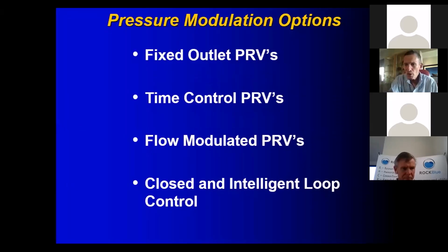Now, when you're using a pressure reducing valve with a pilot, you typically create a fixed outlet pressure going into the zone. So you have a zone of maybe 5,000 or 10,000 properties, and you have a fixed pressure going into that zone. The objective is that at your critical point, you get a pressure of roughly 20 meters, 25 meters at the maximum demand. So when the friction losses are highest, you should have 20 meters at your critical point.